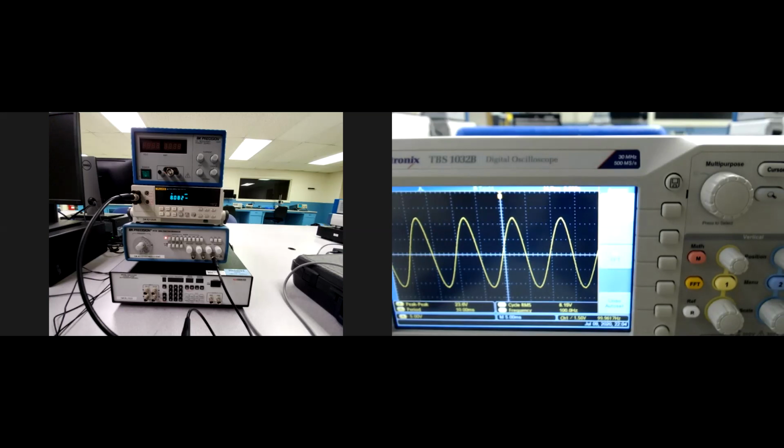Okay. Now, Ryan, I'm gonna keep bugging you. If you can help me with step number 5. Adjust the amplitude on the function generator to an output of 5 volts RMS and 100 hertz, sine wave.